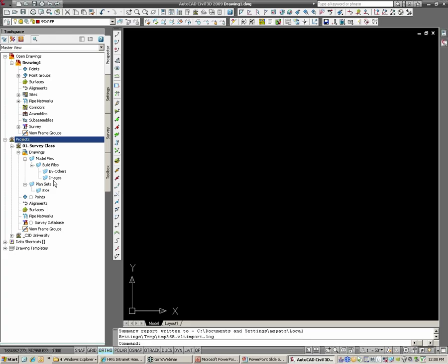All right, so that builds us a project in here, and it puts that in the Vault. And really, the template gives you this folder structure here. Next part of this is we always want to start a drawing from a template. So we want to start that initial drawing here to bring this information in. To do that, we always want to start by right-clicking on the templates down here and hitting Create New Drawing.